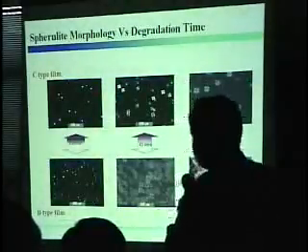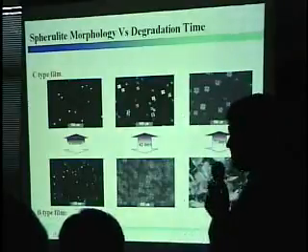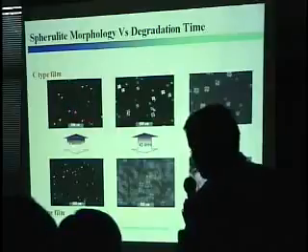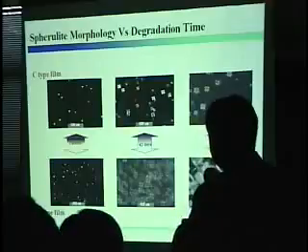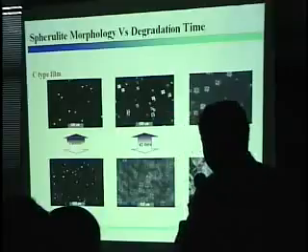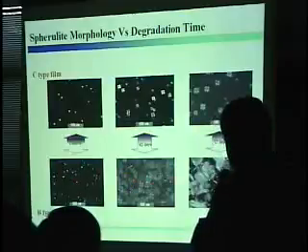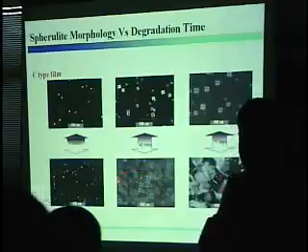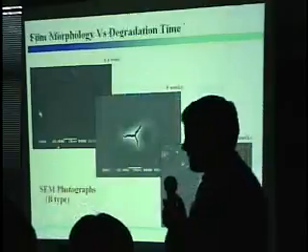Next slide, please. These are polarized microscope photographs of the spherulites in this film during different degradation periods. Here, with no third component, only PEG and L-lactide, the number of spherulites increased with growing size over the degradation time. And here, where the third component was applied, the number of spherulites rapidly increased in excess, and the size also increased, but here the size shows broken spherulites. Next.